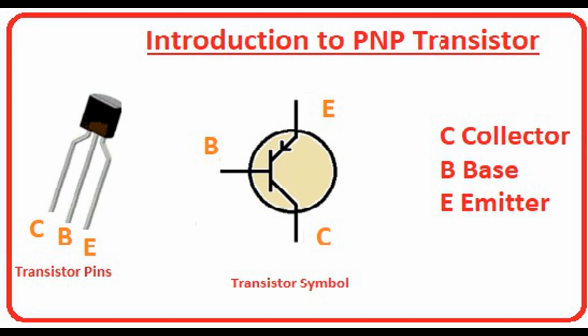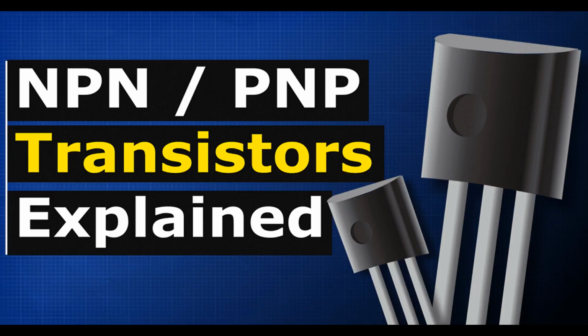N-type materials are fundamental components in the construction of various semiconductor devices, including NPN bipolar junction transistors, BJTs. N-type regions are often used for the collector and emitter regions in NPN transistors, allowing the controlled flow of current between the emitter and collector terminals through the movement of electrons in response to a base current or voltage.